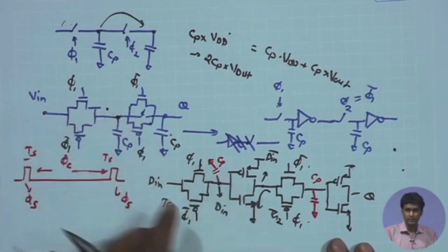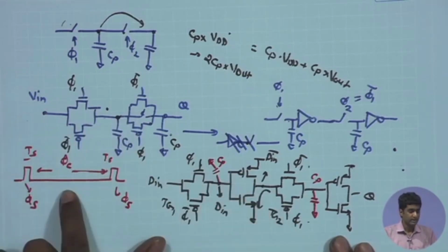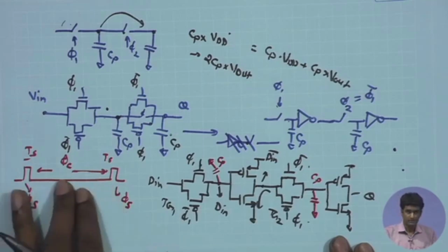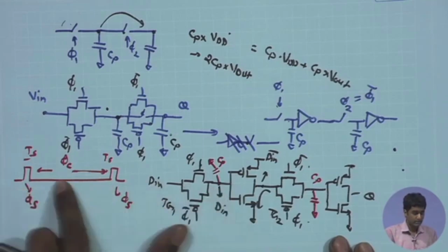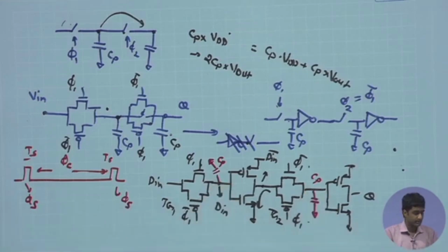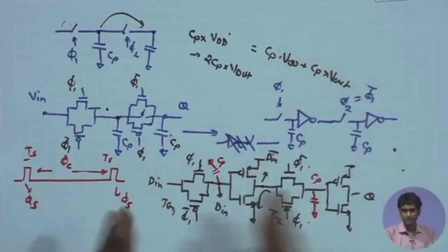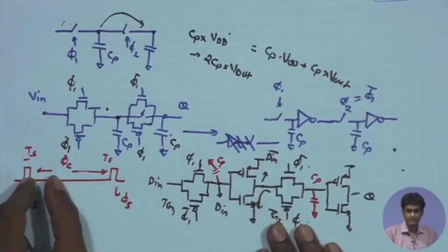And likewise, in this particular example, in general we are having a lower clock frequency. As a result, a significant deviation in these voltage levels can be expected, especially if you look at the last flip flop, that is the MSB flip flop of the counter, which definitely has the longest duration of data retention.